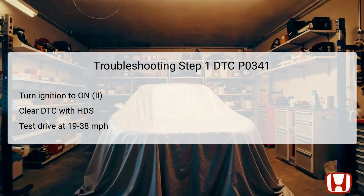The first step in troubleshooting DTC P0341 involves several critical actions. Begin by turning the ignition switch to the on position without starting the engine, which allows the vehicle's electronics to engage. After this, use the Honda Diagnostic System, HDS, to clear any existing DTCs. This step resets the vehicle's computer and can sometimes resolve minor glitches.